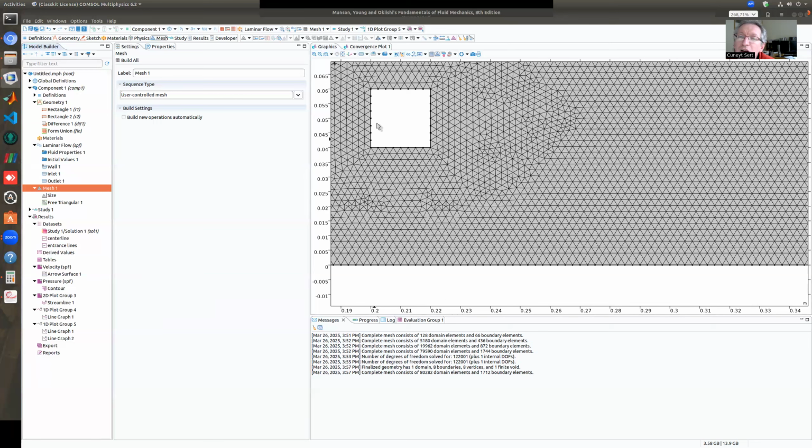If this is not working, bu da çözülebilir. It is possible to solve this one also. But we have to generate a proper mesh, not like an arbitrary one I'm doing here. So we have to be careful. If you try to go really, really fast, it may not be possible to get a nice converged solution. So I'm not saying that this is an impossible problem to solve. Obviously, we can solve it, but maybe not with this mesh, maybe not with these settings. A circular obstacle would be easier to handle because it's smoother and then everything will be easier that way.